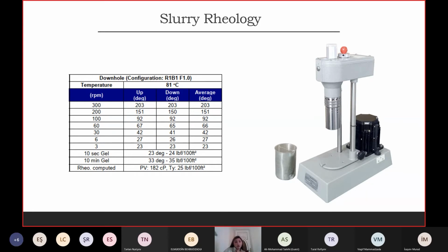The same goes for rheology. Mud rheology is lower than spacer rheology, and spacer rheology is lower than slurry rheology. You can call it density or weight, okay? Don't confuse them. So mud lower than spacer, spacer lower than slurry. Densities and rheologies. It is applicable for both parameters.